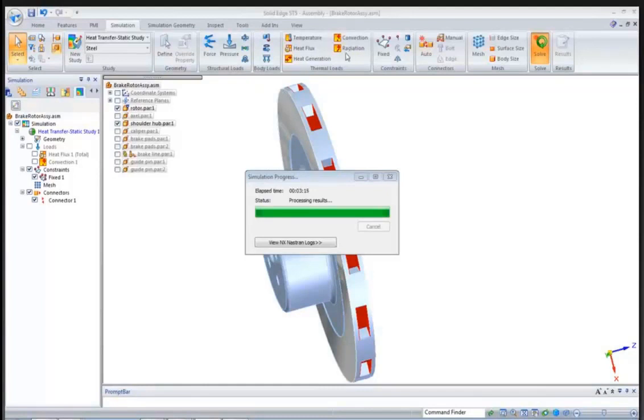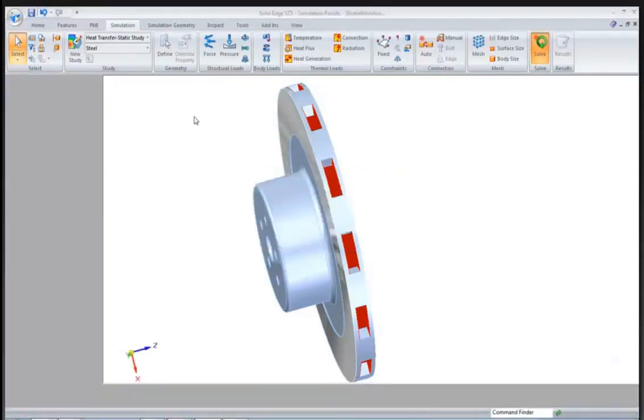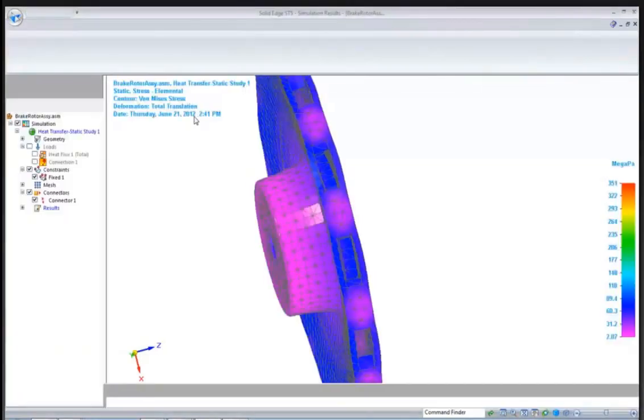Now, the last form is radiation. So with radiation, you've all stood out there in the sun. It's just electromagnetic waves carrying photons, so you don't need a medium for them to transfer through. And you've got the Stefan-Boltzmann constant, which says that the surface temperature to the fourth power times the Stefan-Boltzmann constant. That's the Stefan-Boltzmann equation. And then you multiply that by emissivity to get the heat flux. The emissivity is another material property that you look at, and an ideal radiator is a value of 1. It radiates perfectly, it's a value of 1. So everything you're going to do is going to be below 1.